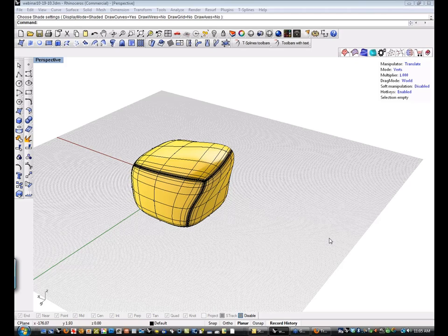There's actually, we don't really give you a choice. It exports so it's mathematically watertight. You'll get the same shape, and that's one of the reasons why T-splines is growing and useful for CAD. NURBS compatibility means your NURBS shape will be exactly the same as your T-spline shape.